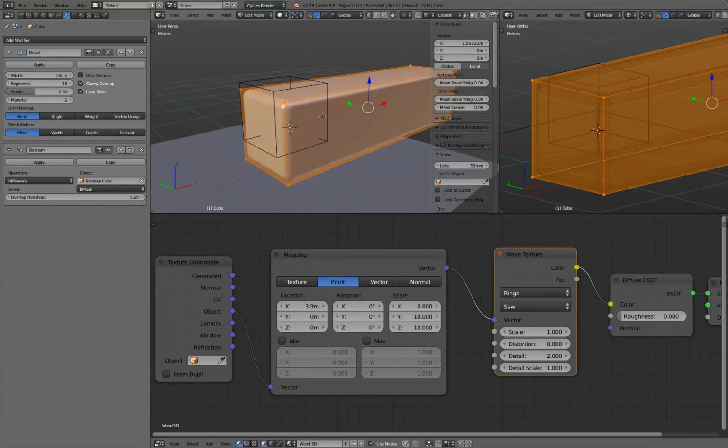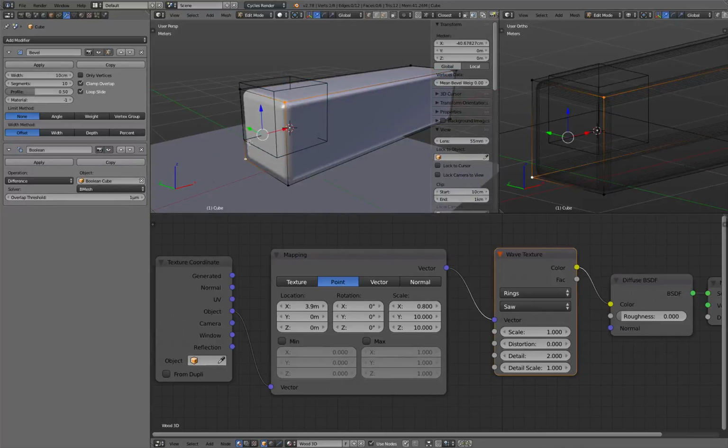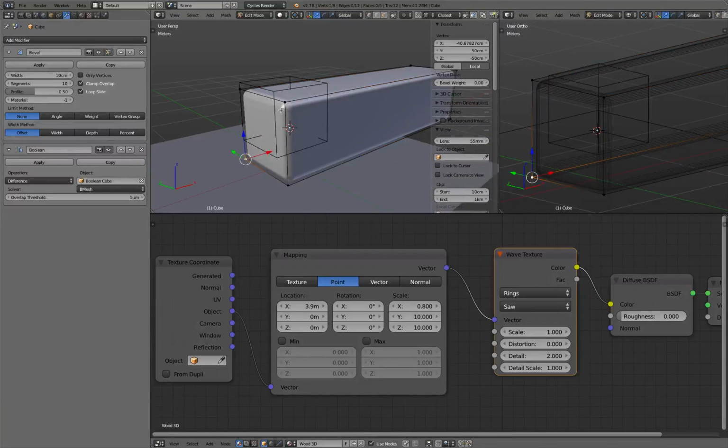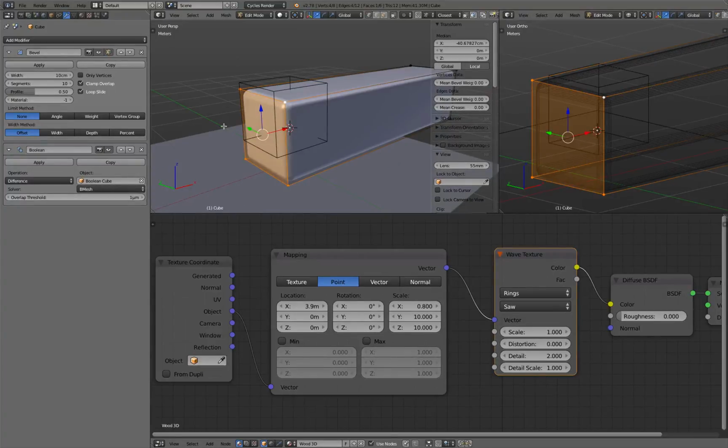So in edit mode I can, for example, select those 4 points. So it selects the 3D cursor, it puts the 3D widget at the center. I can also simply select a diagonal, because currently this is actually a symmetrical object. You see it doesn't change anything. And then Shift S and cursor to selected.